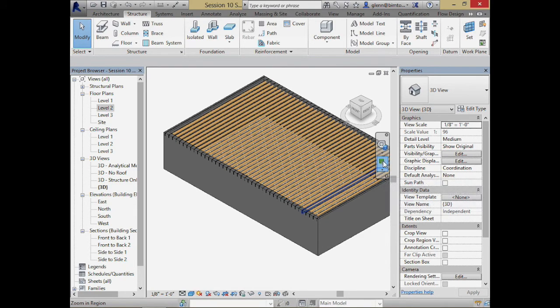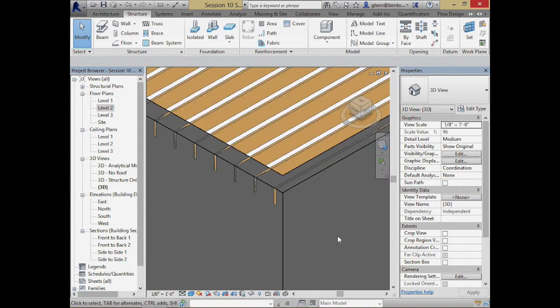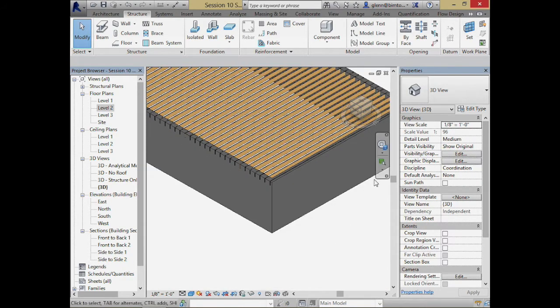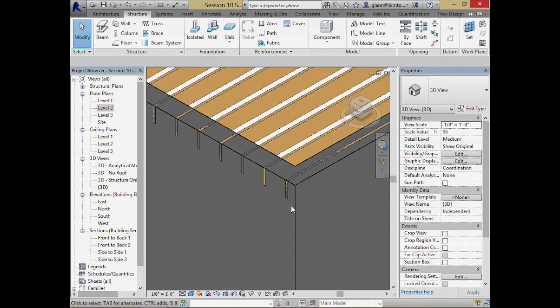So this is a very common way of framing things. In a lot of wood frame construction, we do something like this. And the neat thing about it is if we have these joists spaced closely, if it really is every 16 inches or every 24 inches, something like that, the amount of load that is coming down on an individual spot is not so great. So you can actually just, in the strength of the wall itself, carry that. We don't go through and crush anything because there's really not that much load. Okay. So that works in light frame construction.